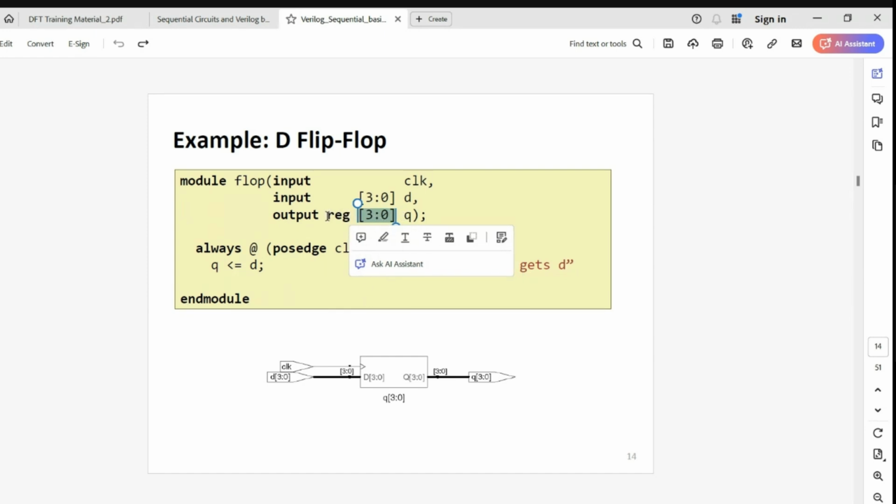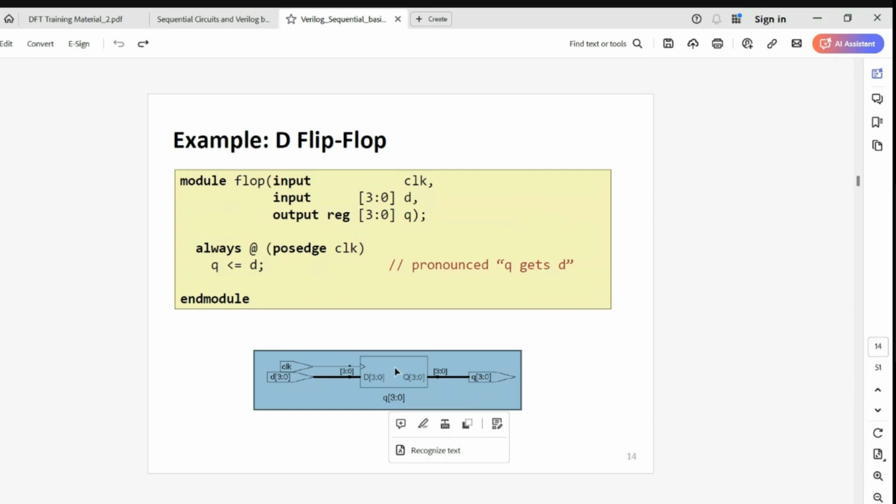Okay, so this is syntax in writing the code. If you want to store the data after processing, between input and output there will be functionality, right? So this is your input and this is your output. Something is happening here. That means this is a flop, right? Definitely for a flop you will write register. You are telling that to store data.